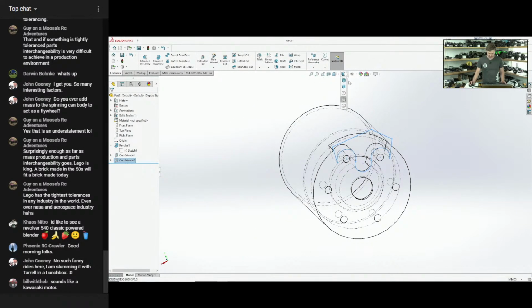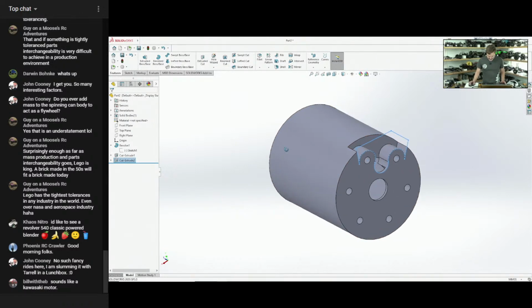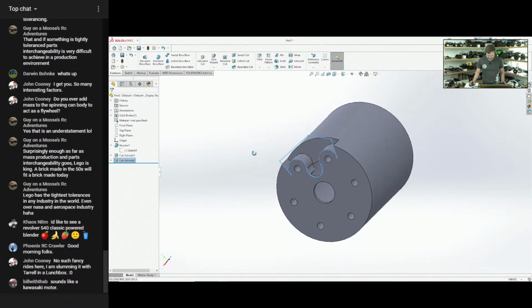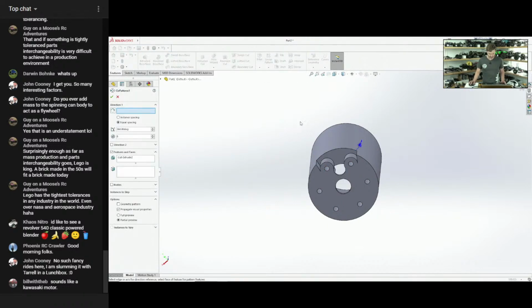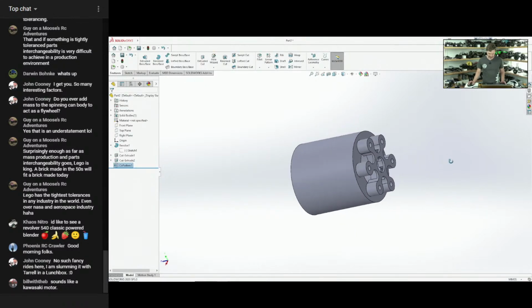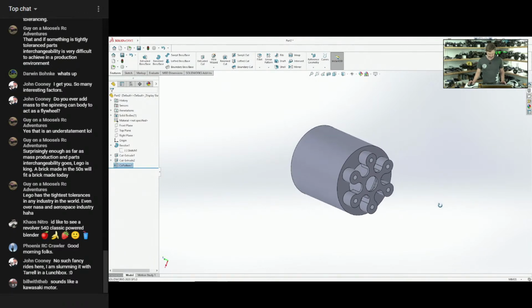We're going to press F for respects. We're going to go back to this view. Oh, look at that big old cut where the bearing is. Maybe I should import a ball bearing as well. See how it looks. Yeah, that'll be interesting. Whatever, this is just for fun. Now what we're going to do is copy this into a circular pattern around the can. So direction 1, basically any round object. We only want 6 of these guys. There we go. Oh, look how lightweight and fancy that looks. It's like some revolver cylinders.